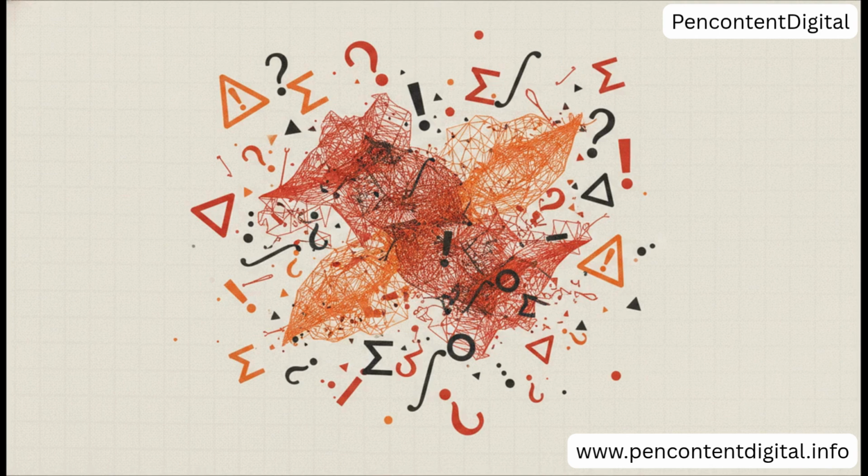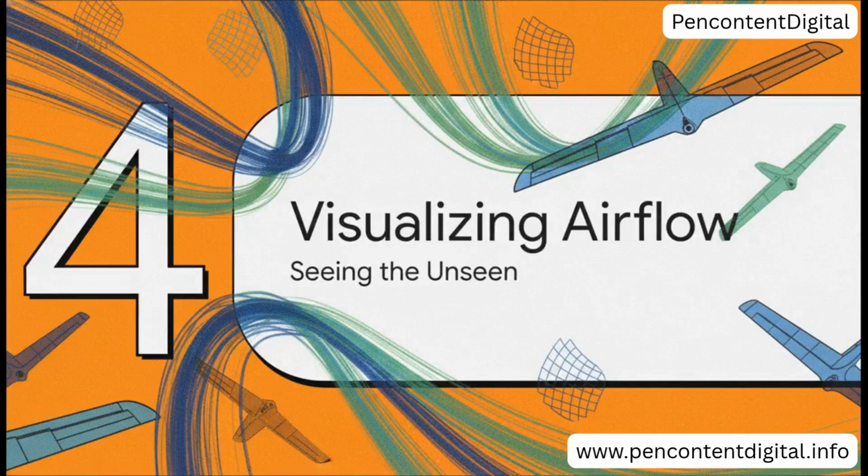If your mesh is too coarse, you lose all that crucial aerodynamic detail and your accuracy just plummets. And if you ignore whether your mathematical solver has actually reached convergence, your results are essentially useless. So it's a very delicate balance between careful, precise setup and computing feasibility. Which brings us to Section 4, Visualizing the Invisible.